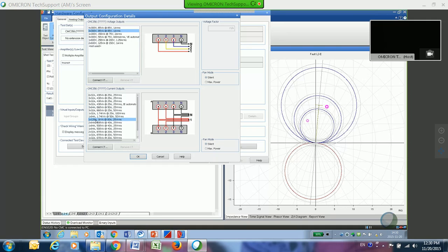And if I want to get 128 amps out of it, this is my configuration that I would use. And so 1 and 2 on both A and B are combined together to get the polarity part or that channel out for 1. And then my neutrals would be connected to 3, connected together, and also my neutrals together on both channels A and B to provide my return for my currents.